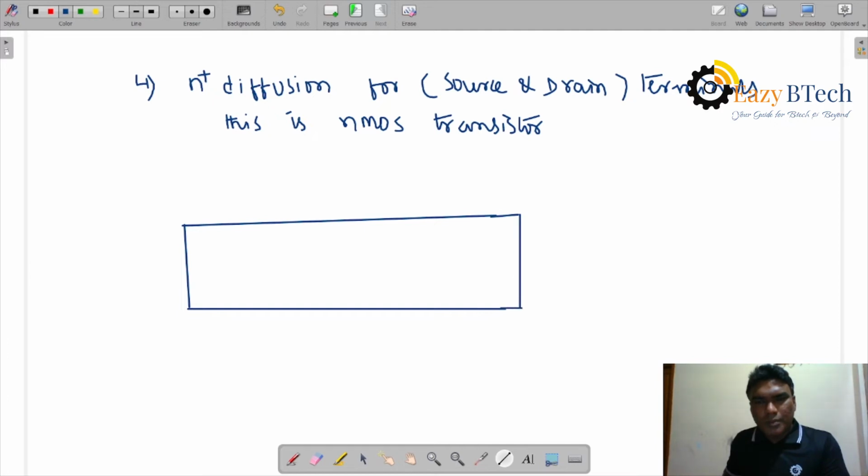So the bottom area is the N-type substrate, with an active window and SiO2 layer. Then we diffused here a P well. This is a P well. Afterwards, thin oxide and polysilicon for gate formation. Thin oxide 0.1 micrometer, polysilicon as a gate terminal.